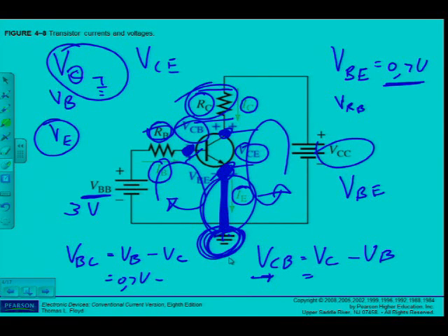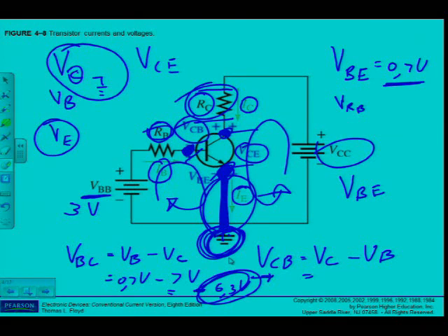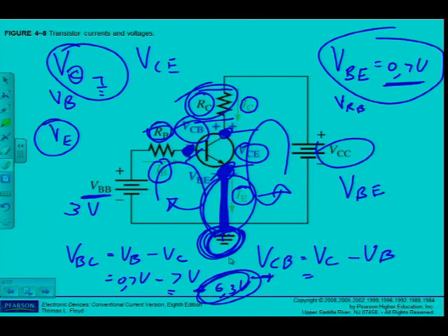Say, for instance, it's 7 volts. But what I'm getting at is this answer will be negative something. Say negative 6.3 volts. What does that indicate? That the base collector junction is reverse biased. Very important, né? So the base emitter junction is forward biased. We've seen that, 0.7 volts. But the base collector junction is reverse biased. It gives me a negative voltage, as you will see later in the calculations that you're going to do.